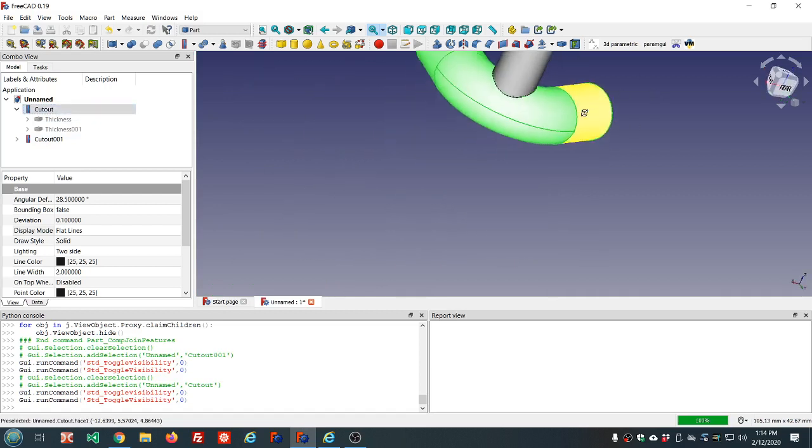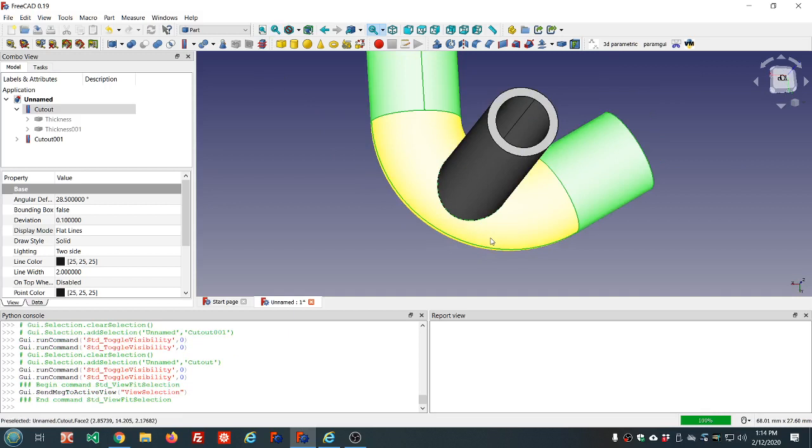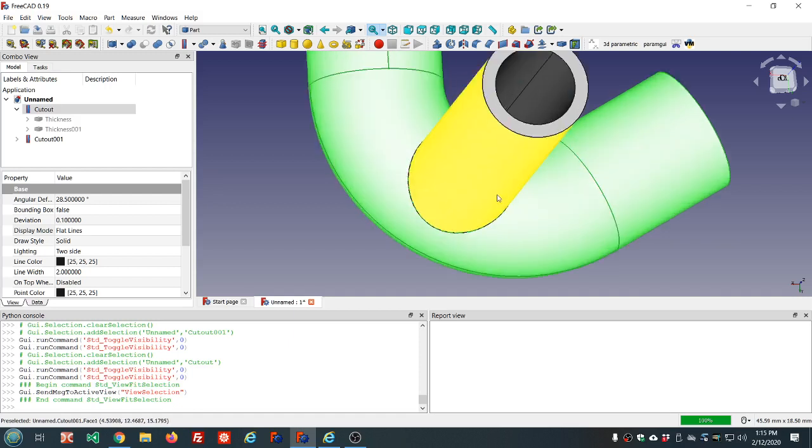But whenever you do an operation like this, you have to consider that if the object going into a hole is the same size as the hole, you need some clearance for that. It might just be a tiny fraction of a millimeter, but generally, if you make them both the same size, they'll never fit together. You might have to get a file out or something. So you would want to perhaps adjust for that.